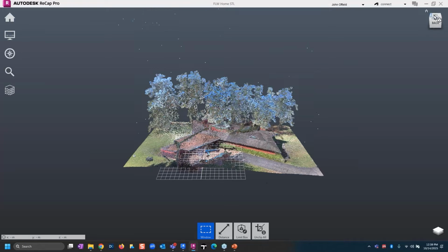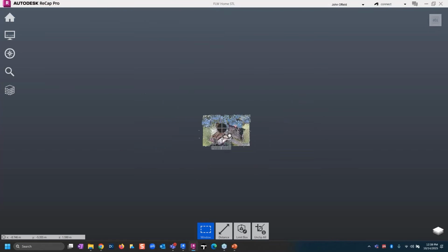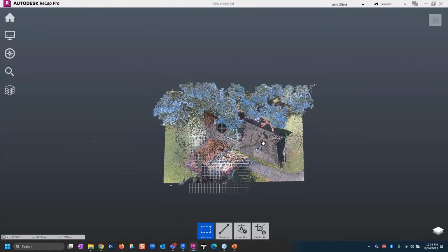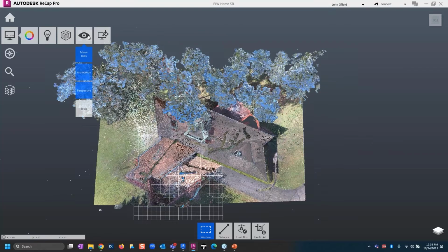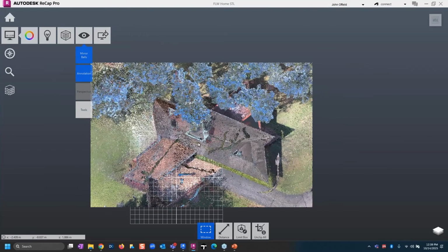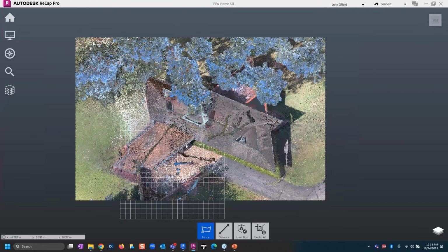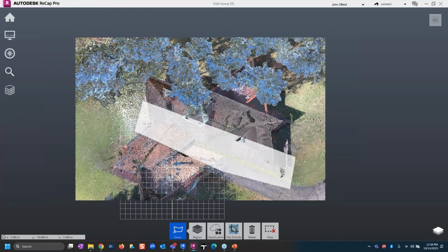Well, I want to jump back into this top view, and we're just going to chop off a portion of this house here. So let's go back in that ortho type view, and I'm just going to use this fencing tool here. I'm just going to tell it to have starting points, and notice that you can pick wherever you need. Double click to stop that or close it out.